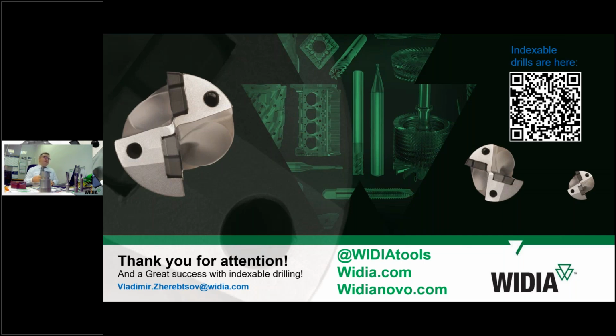If you do dry cutting, I would check on different depths. For example, if you need to cut 3 times D, try to go to 1 diameter first. Look if everything is okay, no chip jamming, no strange sounds. Go to 2D and then to 3D. Then increase the length of all passes, and then increase to the final pass.